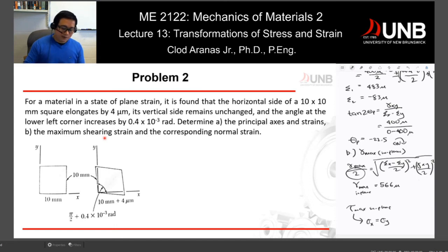That's always true if you are at the tau max in plane. We showed it if you go back to lecture number 2, from the waves that we plotted before. If you track your maximum in-plane shear stress and check the value of the stresses at those points, you will end up with this number right here.